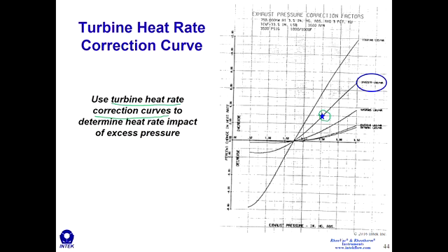This measured pressure, for the condenser that we're evaluating, is operating at 2.5 inches. I know this is very difficult to see, but this says 2.5 right there. And we calculated our target pressure using the methods that we just talked about on the previous slides. Our target pressure is 2.0.